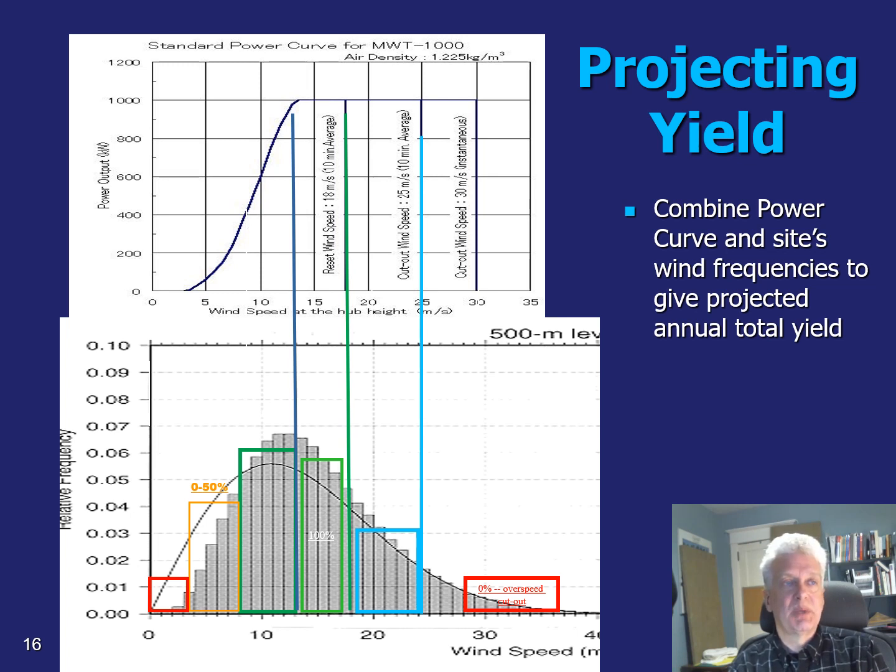So the cutoff speed, down at less than 4 meters per second, is the left-hand red square on the Weibull curve. That's an area where, in those statistical bins, you don't have any output. When the wind speeds are in the low end, on the lower slope of the curve between 5 and 10 meters per second, I've drawn an orange box around those, and you can see that there's a bit more frequent cases where the wind is at those speeds, and then you would have below your rated capacity, you'd have 200, 300, or 400 kilowatts rather than the 1 megawatt rated power.